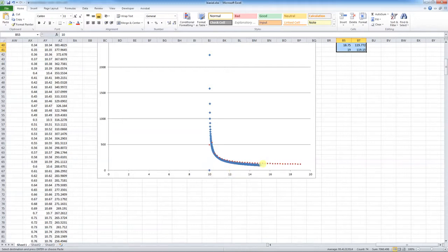For the red dots, that's the finite element solution. And you notice our stresses are a little bit higher even out in front of the crack tip. We have a finite width plate, and we use the analytical solution for an infinite plate, and so forth. So there's a little difference there. But you see that it's very nearly following that analytical solution. It's picking up this curve right here. We had to get a ton of elements to pick up that curve.